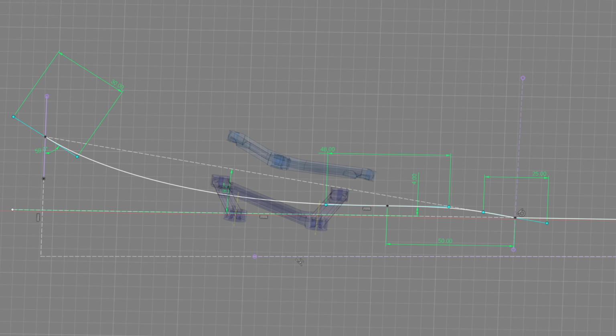So this here is the side profile of the diffuser, and it's actually what's referred to as a double kicked diffuser. This is a common diffuser design used in a lot of race cars. The first kick-up or throat point is just ahead of the rear suspension so that we can generate some downforce further ahead on the car. And then the diffuser is actually straight for a bit where the rear suspension mounts to the monocoque, and then it kicks up again after the rear suspension has been cleared.